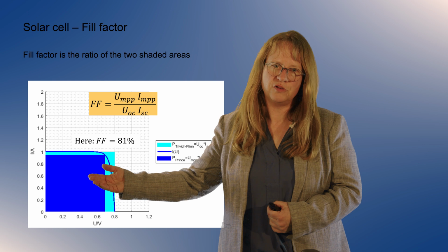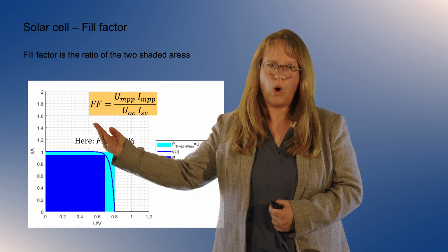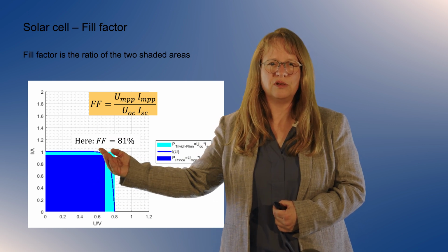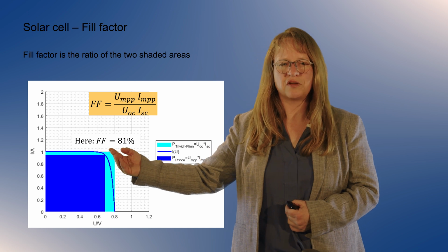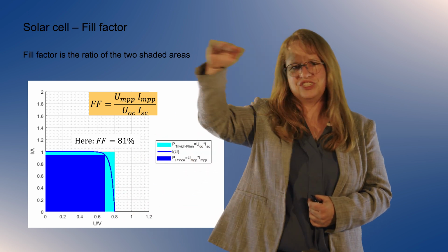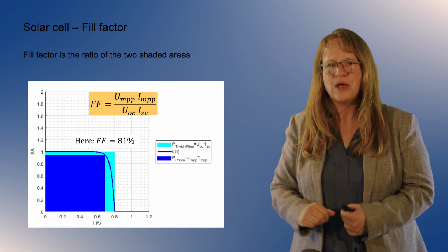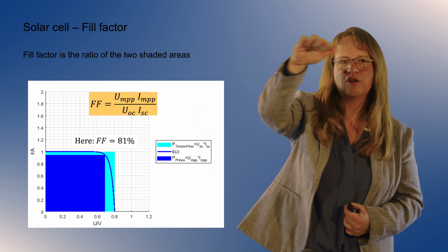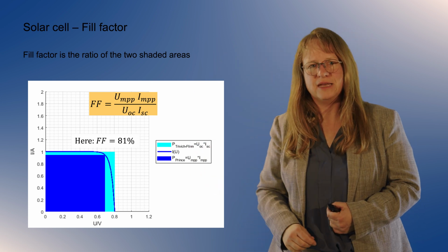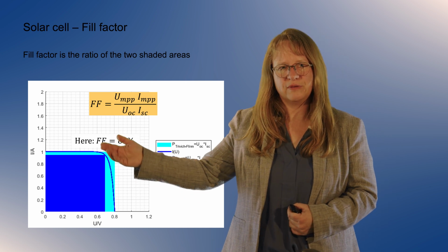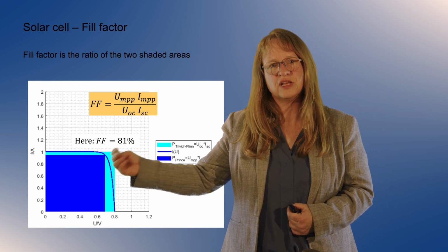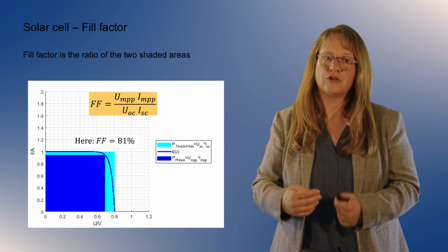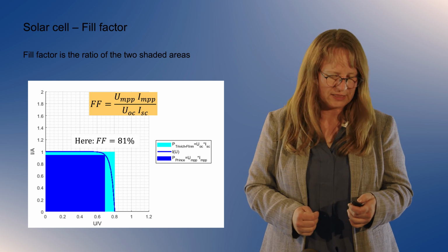So that means if you have a fill factor of 1, then you would need to have a solar cell with a characteristic that is an ideal edge, kind of. But that obviously you won't have for a real solar cell, but you have some IV curves with some bending. And therefore you have this loss that is due to the electrical characteristics of the solar cell.